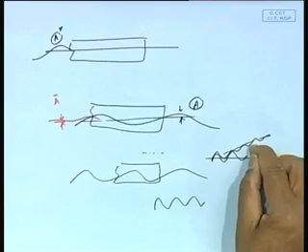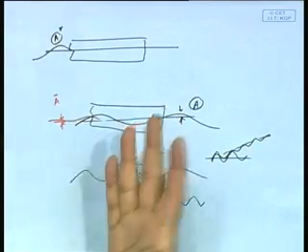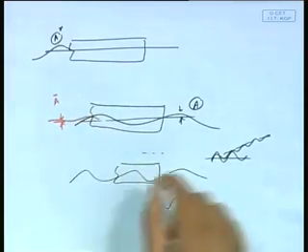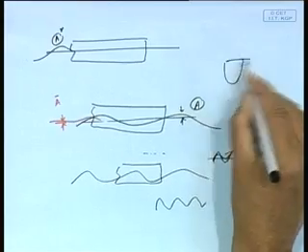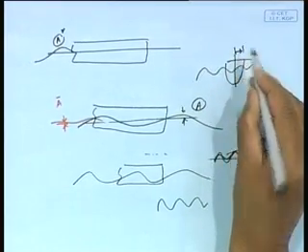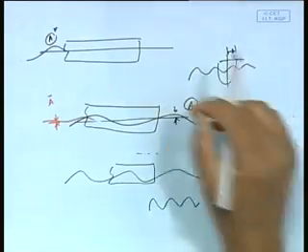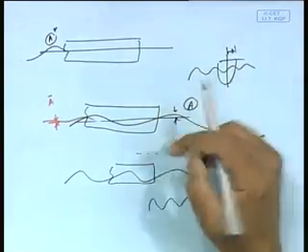This drift force cannot be explained by first order theory, because first order theory tells me my xi1, the surge or sway motion, is oscillatory about a mean location, but reality shows it drifts. This drift is obviously occurring because some kind of mean force is acting on the body. So, there is a body here, waves are coming here, a net mean force is acting, and this is a second order phenomenon. This mean force is what we call the drift force.